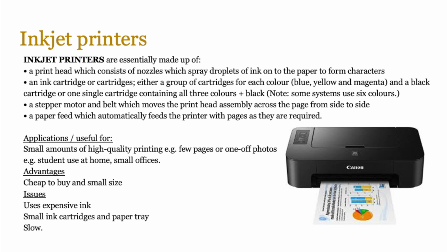There's a stepper motor and a belt which moves the print head assembly across the page from side to side, and a paper feed which automatically feeds the paper as required. So what are they used for? Well, they're used for high quality printing. When you want a few pages or photographs, chances are that you would use an inkjet printer. They're cheap to buy and they have a small size. That's the benefit. Their color reproduction is far superior to laser printers.